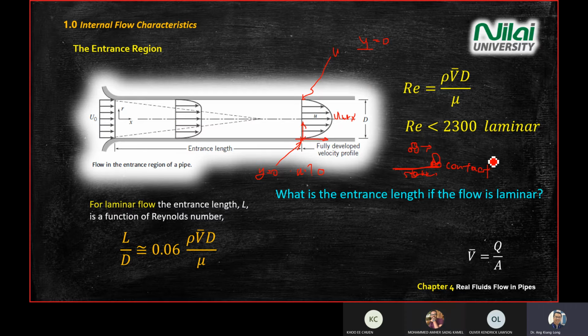You understand viscosity? Yeah. So if there's no resistance over here at the center, you can say there's no resistance at all, so you can move at the maximum speed. If you're coming in at 10 meters per second, wherever you measure at the center, you'll get 10 meters per second, assuming you have a Newtonian fluid.